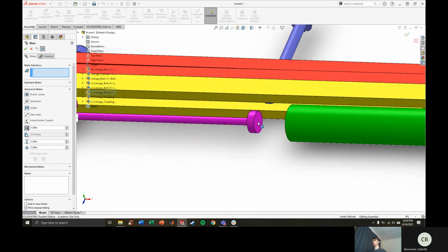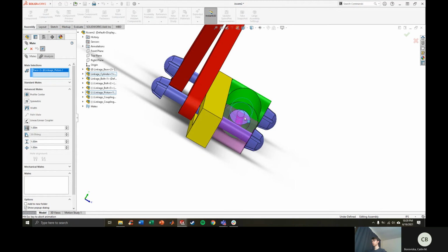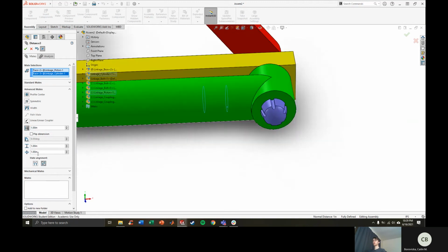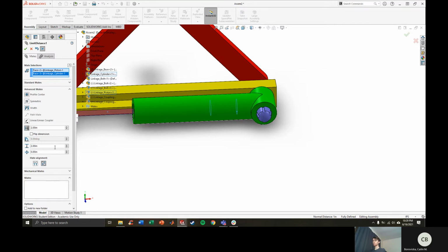So let's again select the face of the piston and the internal face of the cylinder. And we can come over here, hover over that, that's the minimum value. So these can touch, theoretically. So we can set that minimum value to 0. Maximum value, I don't know exactly how long this part is, but I don't know, 2-3 inches maybe. More than that, 5 inches.